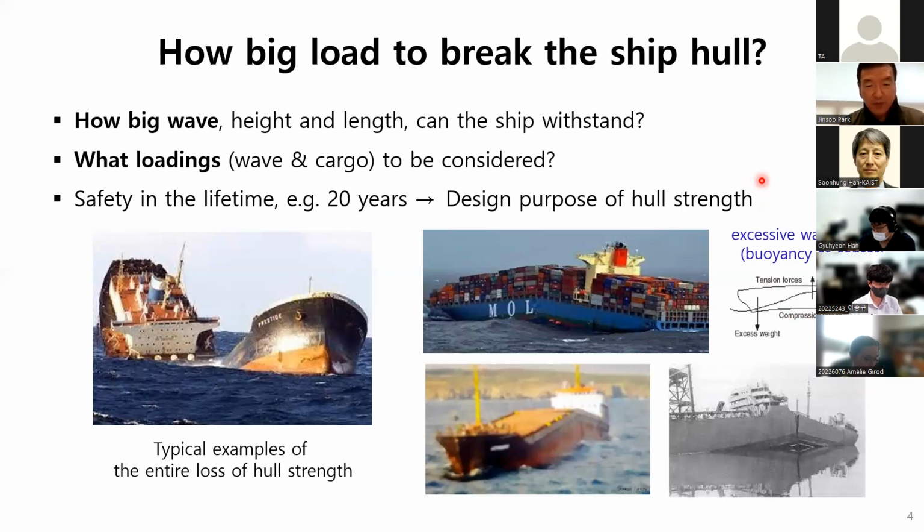Basically, a ship is designed for the maximum wave loading of 10 to the minus 8 probability. That is the most serious wave among 100 million waves that the ship is expected to encounter.